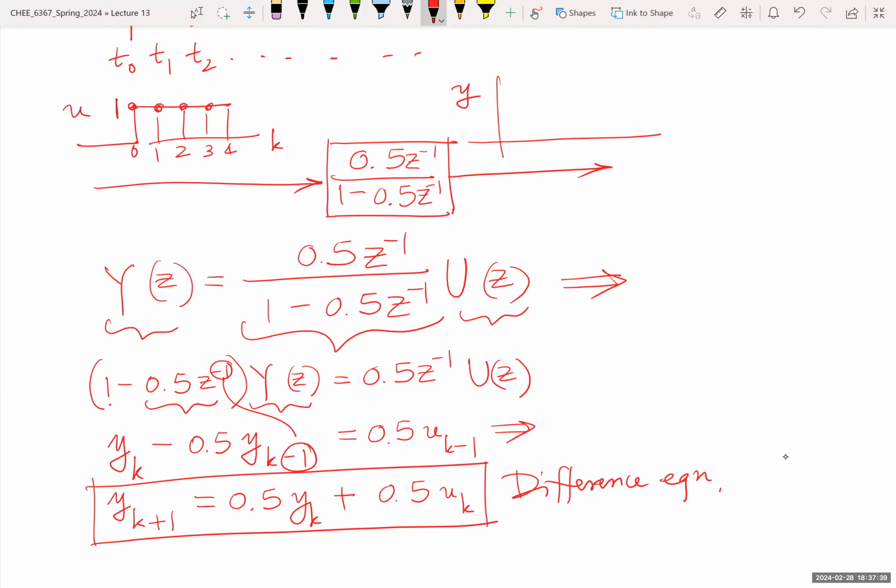And those equations are used all the time, not only for controller design and for simulation, but also for identification. In practice, the common problem is to identify these two, which is going to be our next chapter in the notes. The identification PDF that describes how we can take experimental data and find these numbers.